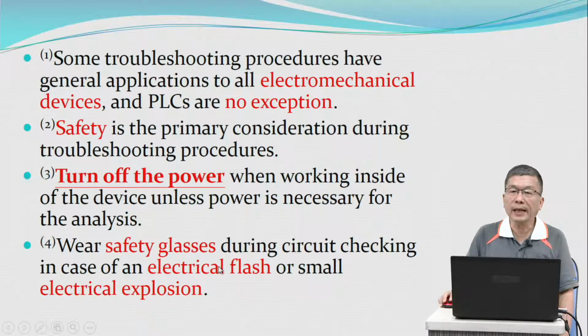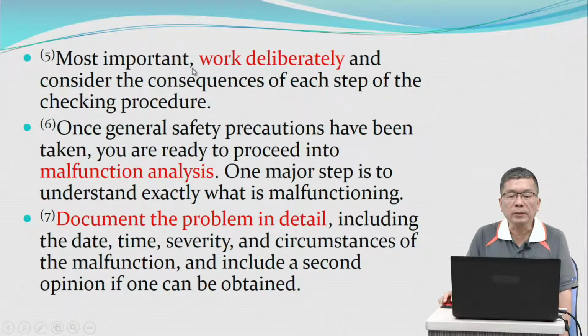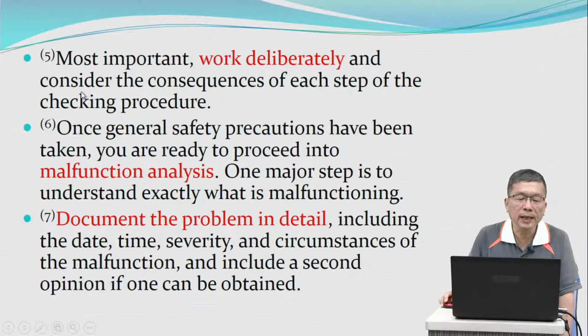Wear safety glasses during circuit checking in case of an electrical flash or small electrical explosion. Most important, work carefully in the laboratory and consider the consequence of each step of the checking procedure.